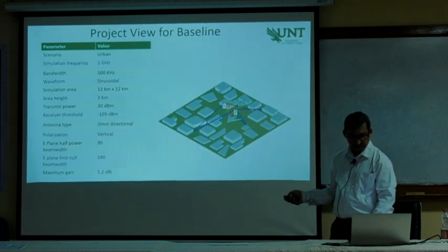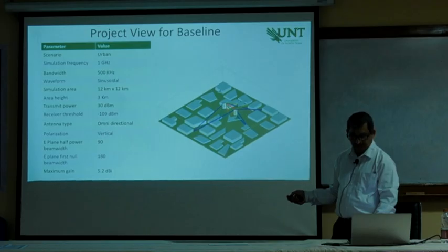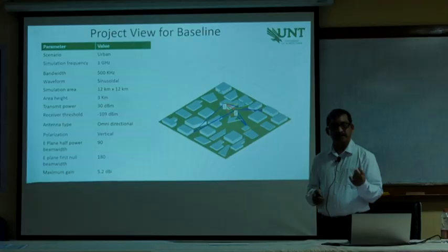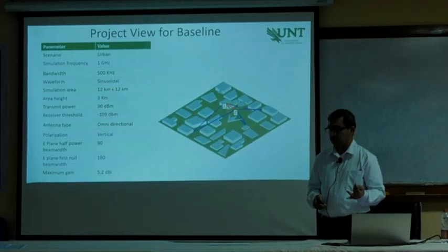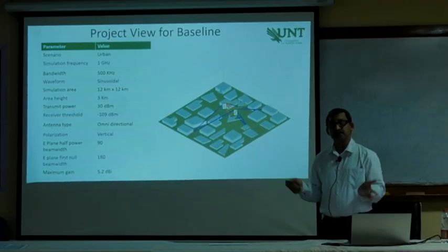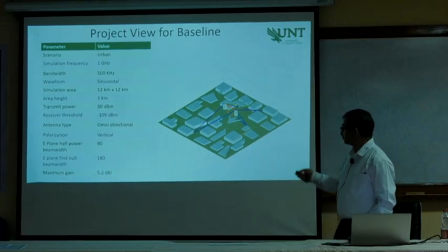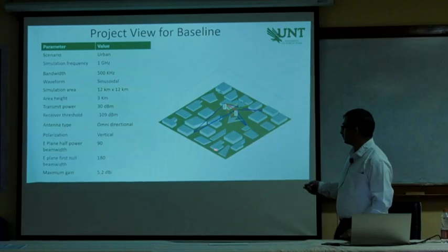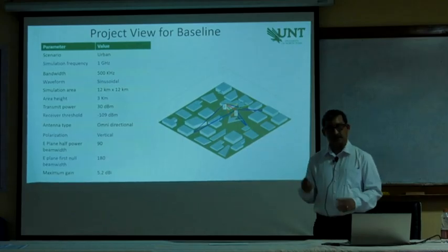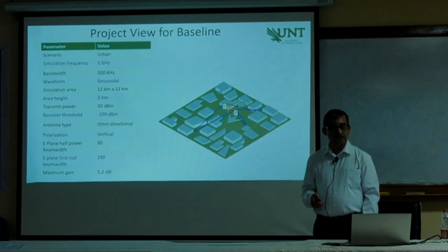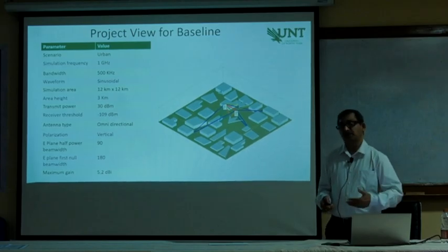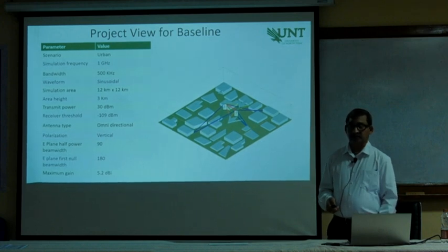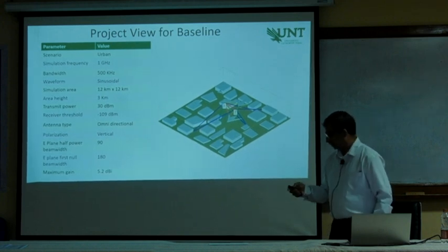But key thing is, set up the configuration and then start doing the experiments. You can measure, you can get line of sight, non-line of sight, how many non-line of sights are there. All this is done by the tool. So it uses this to figure out how many, depending on where you kept the transmitter and receiver, it gives you all the reflected components or non-line of sight paths. And then it gives you all those power delay profile, delay spread, RMS delay, all those things.